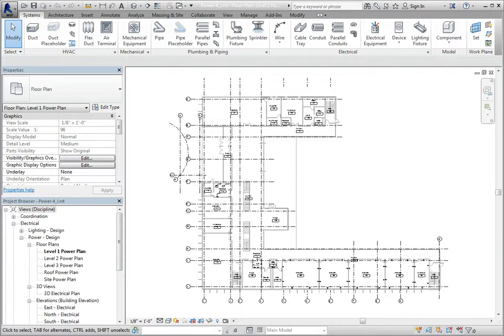Revit calculates the wire sizes for power circuits based on the size specified for circuit protection, voltage drop calculation, and correction factor. Wire sizes are automatically sized to maintain a voltage drop of less than 3% for branch circuits and 2% for feeder circuits at the outlet furthest from the source. That is, the circuit load determines the overcurrent protection required, which, when specified, then determines the wire sizes required for hot conductors, neutral conductors, and ground conductors.